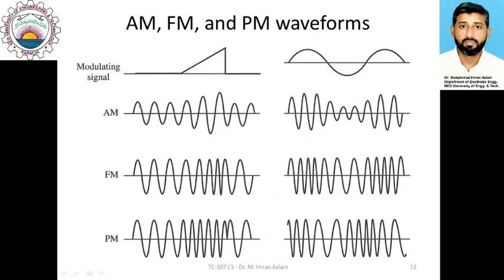So you can see that in the amplitude modulation, we have this constant amplitude which gets increased in accordance with the message signal, and then it suddenly decreases and comes to the message signal value. Similarly, you can see in the FM signal, the frequency is changing with respect to the amplitude of the modulating signal. You can see that starting from here to here, at this point, because the amplitude is relatively high, you see a relatively high frequency or fast oscillation here.